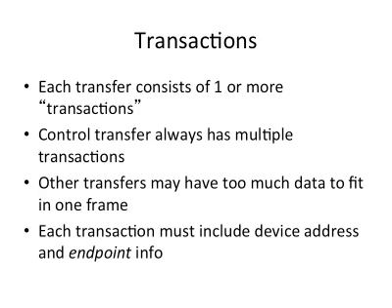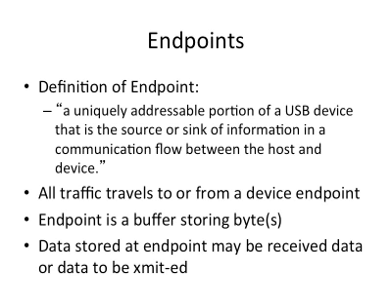Each transaction must include device address and endpoint information. And that's the one we saw. We have device ID and endpoint ID. So what is the endpoint? Endpoint, by definition, is a uniquely addressable portion of a USB device that is the source or sink of information in a communication flow between the host and device.